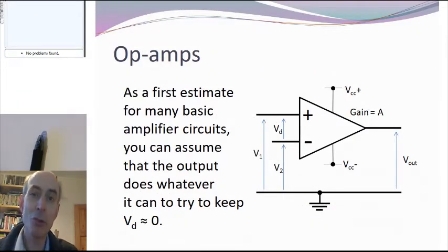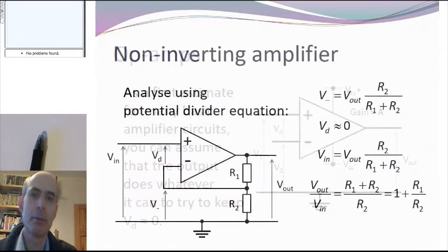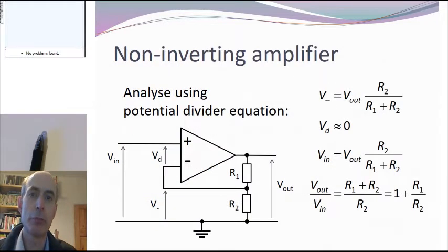When opamps are not saturating, then you can assume that the output is doing whatever it has to do in order to make the difference between the two inputs as small as possible. We've seen this configuration before. If it's not familiar, then go and have a look at the short introduction to opamps on the module website.